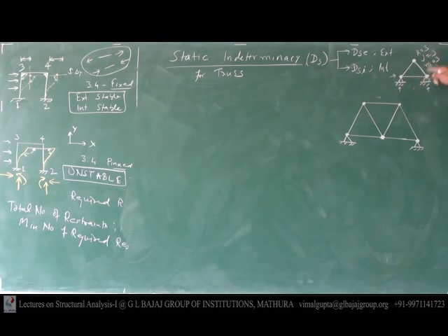It will be called a truss type of structure if all its joints are pin type joints. And one more thing: no load will act away from the joints, meaning all types of load will act through the joints only. Whether the truss is small or bigger, load can be applied through the joint only.